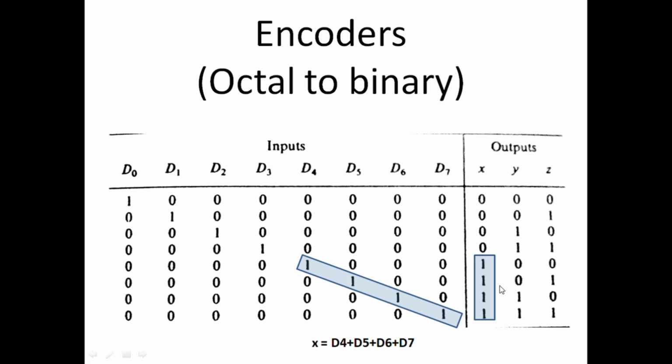We do not need to create maps because it is very simple to write it, or otherwise we would have to write an 8-variable map, which is quite complicated, as only one input variable is 1 at one time.